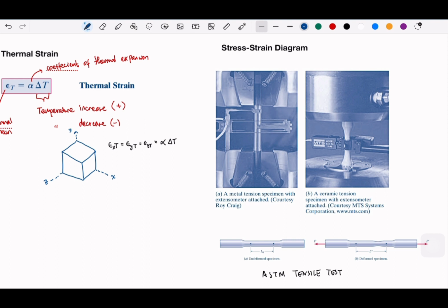Basically, I think every student in the material science major is going to work with this at the beginning, as a principle, because this is where they get the very basic mechanical property or material property that we can develop from this testing. From tensile testing you will get most of the mechanical properties.